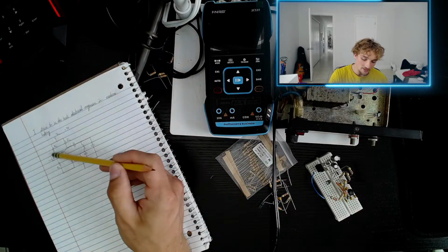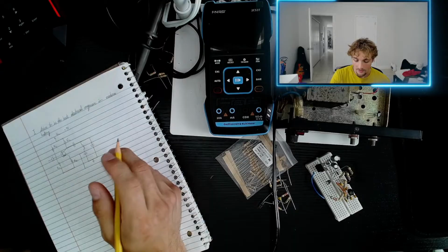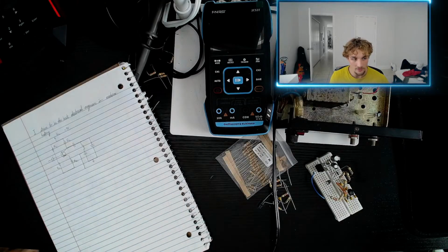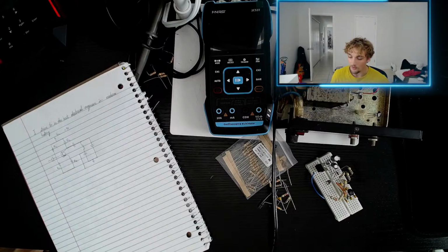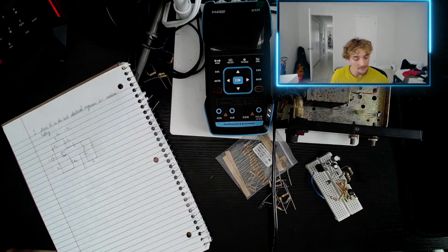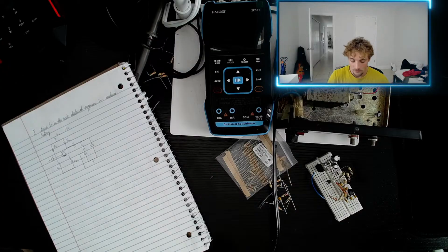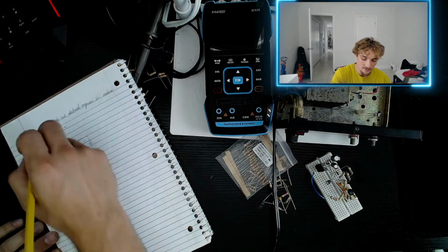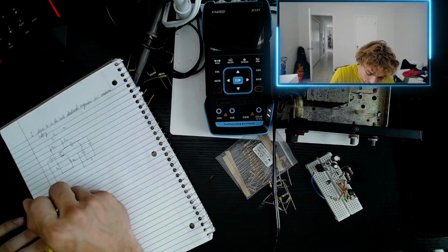Because we don't want any of these parameters to change. That would affect our DC current gain, which is denoted as beta or hFE. This would also, and therefore that would impact things like voltage gain, etc. So we want to maintain that DC bias point at all times. That's why we add these decoupling capacitors.